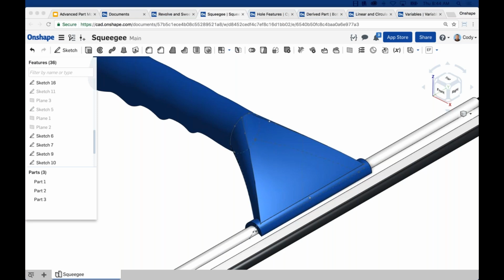Wouldn't Pierce then be very loose, though, somewhere on the sketch? No, the Pierce would be where that curve pierces the current sketch plane, wherever that point is. It is true that it could pierce the sketch plane in two places, and then it's going to solve to the closest. But ultimately, it is that exact intersection of the curve and the current sketch plane. That's the point the Pierce constraint attaches to.